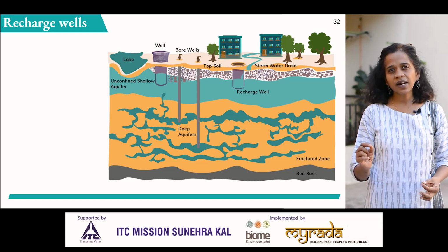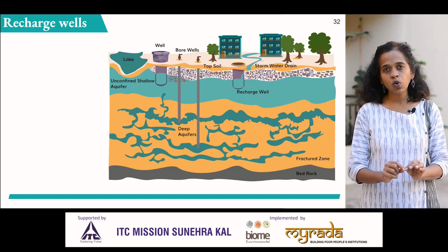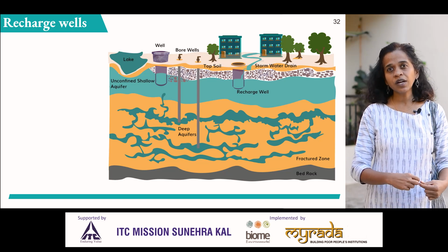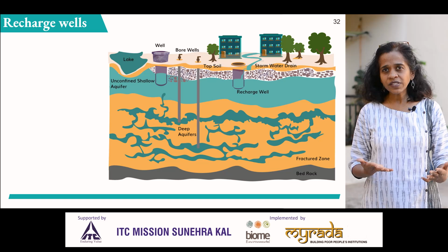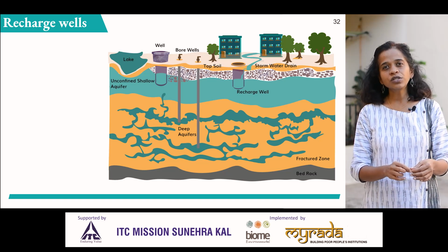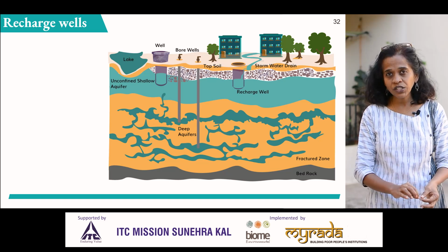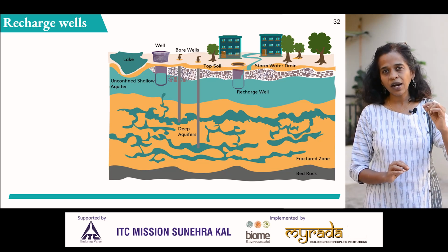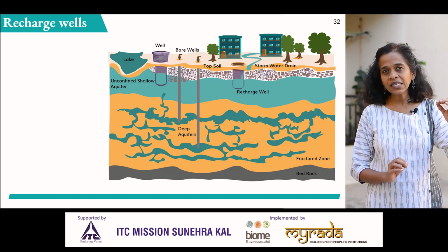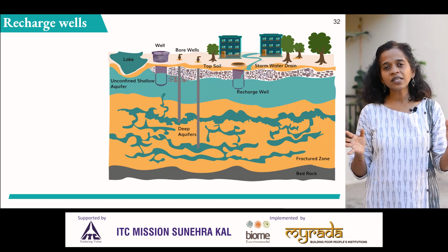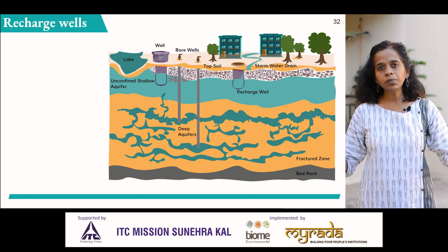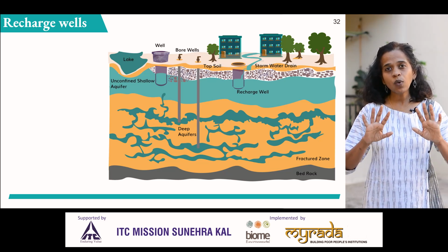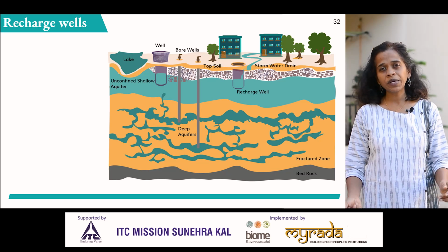In these rocks there are cracks and fissures in which water is held. When we dig a bore well, it is from these layers that we are drawing out water. What we have seen is that you can do recharge to any of these layers. You could be recharging these deep aquifers in hard rock, you could be recharging the shallow aquifer. But what works best is when you dig recharge wells and recharge the permeable zone or the weathered zone. What that results in is that the shallow aquifer becomes saturated over a period of time.